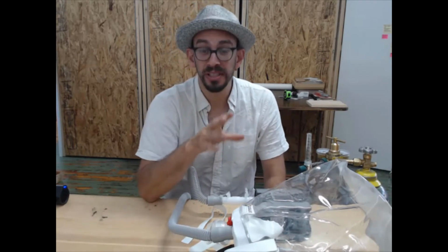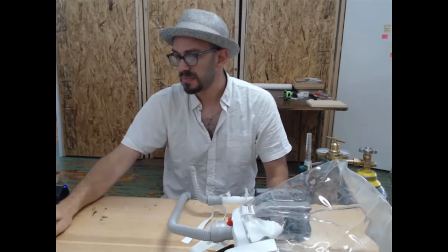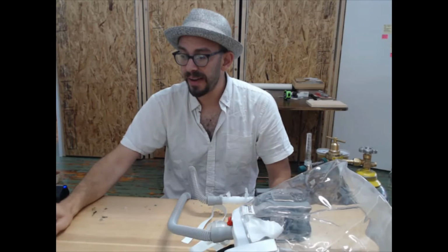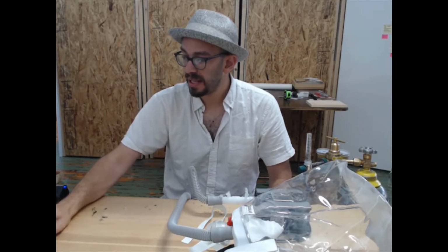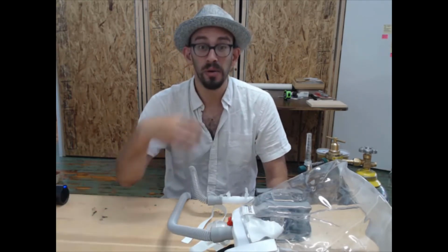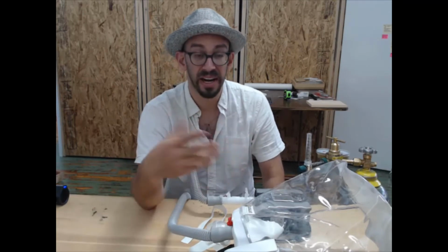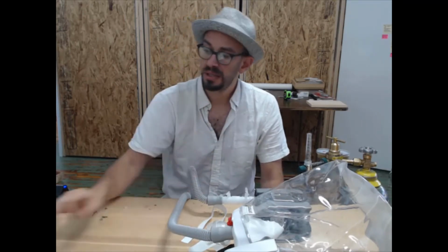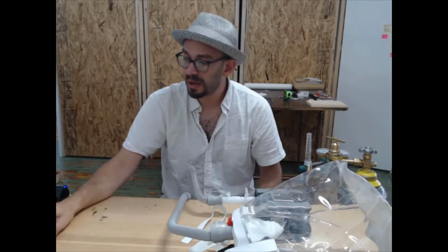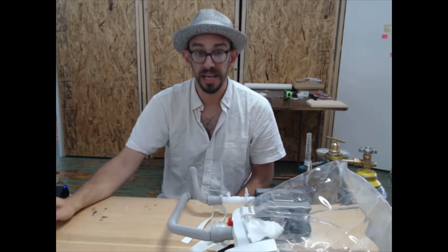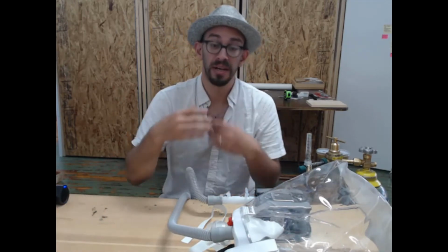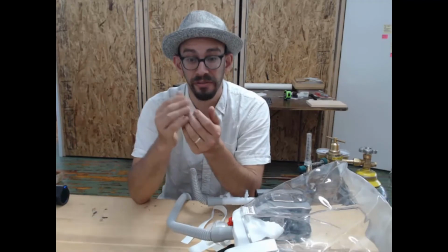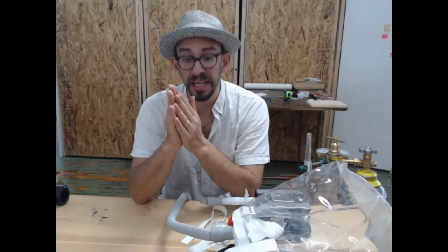How do I make sure I'm using 50 liters of air? Use the values. Every value in this operating table has been tested to show at least 50 liters a minute of airflow going through the circuit. So as long as you are working within the range of this table, you are going to deliver at least 50 liters a minute of flow, and this should be a guide.